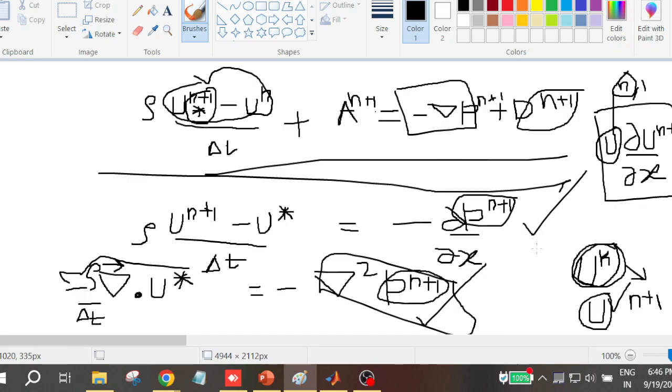Whenever you do a polynomial method, say you write T as a function of ax² plus bx plus c, right? Yes, sir. Quadratic. So this scheme, whatever you do, becomes second order in nature. That's the whole fundamental reasoning why we take ax² plus bx plus c, or sometimes we can take only ax plus b or something like that. You have to see what is the order in that, dT/dx, d²T/dx², I think maximum order. So in that way also you can determine.